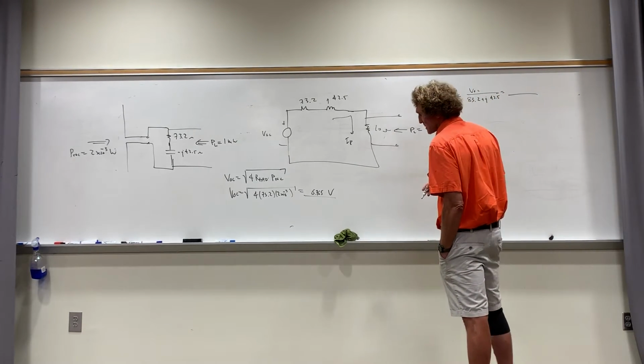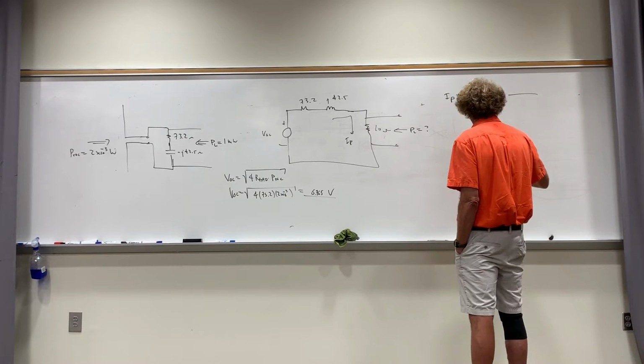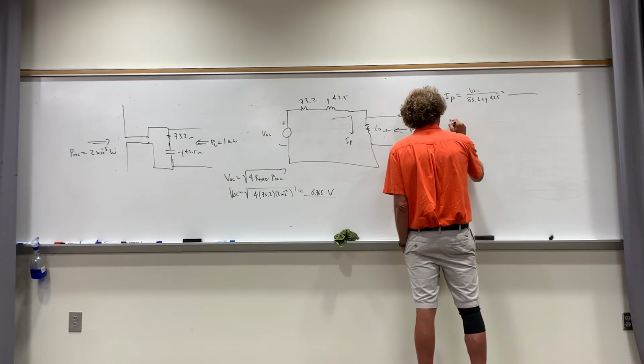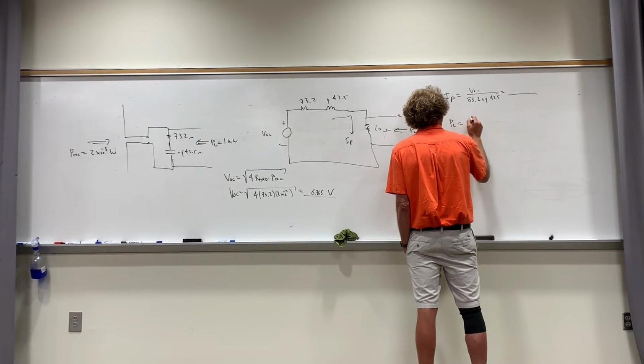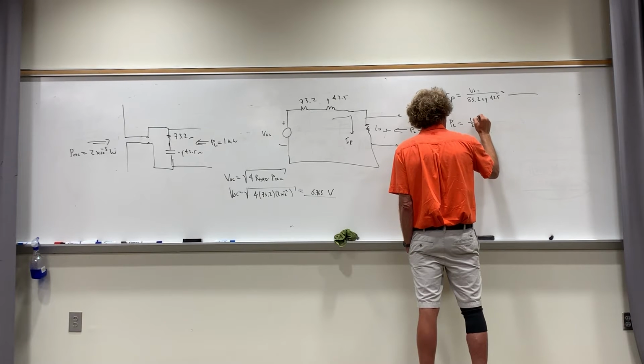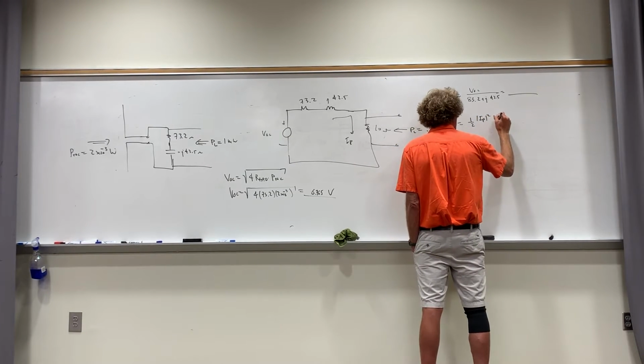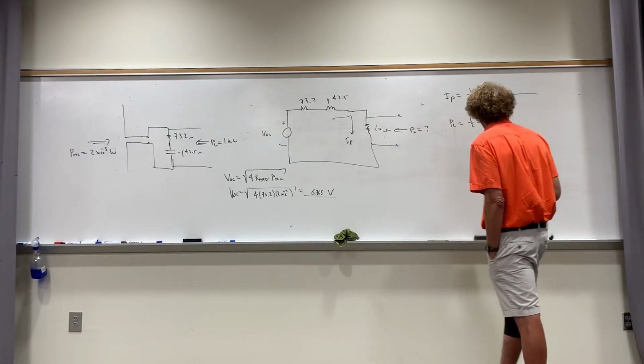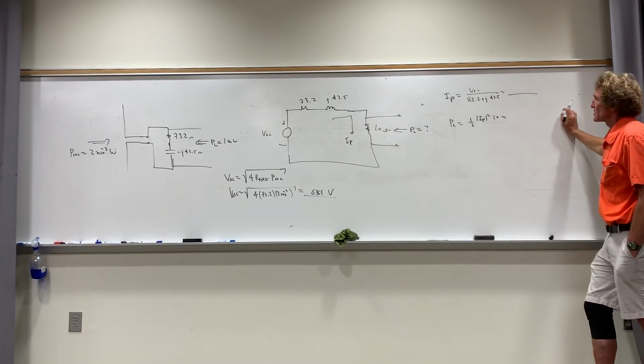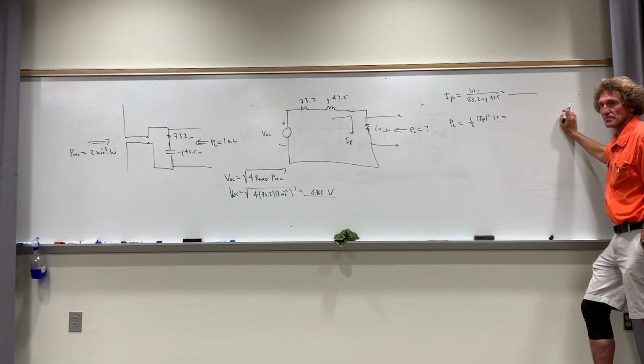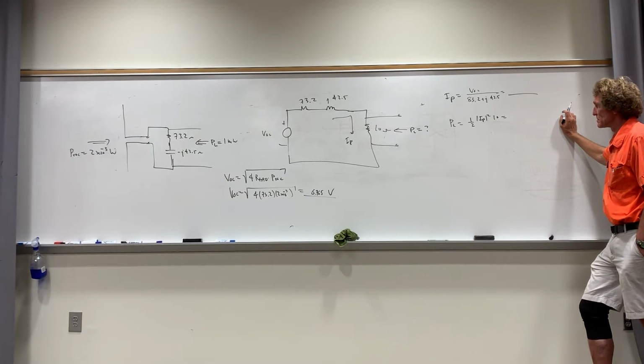And that's 0.765 for V open circuit. Once we get that number, we can get P of the load equal to 1/2 times the magnitude of I_P squared times 10, or really just 5 times I_P squared. First, can you give me I_P on this one? Magnitude only.